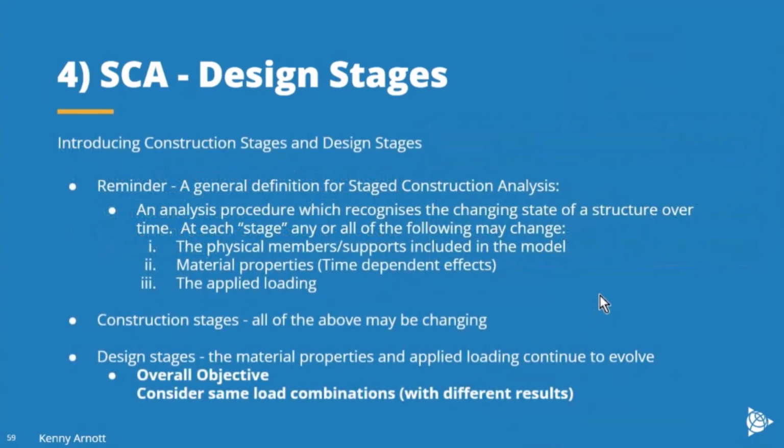And again, a further reminder about what stage construction is. Stage construction analysis is really coming from webinar 1. At every stage in an ordinary stage construction analysis, the physical members and supports in the model can be changing, the material properties changing, the applied loading can be changing. For us in the construction stages, all of the above may be changing, but in the design stages, the model's complete, and it's only the material properties and the applied loading that continue to evolve.